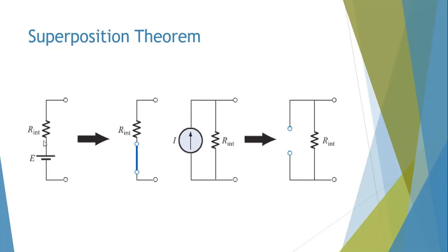So if you want to remove a voltage source, you short circuit it. Now the drop is 0. It's not contributing anything in the circuit. If you had to remove a current source in a circuit, it means you want to make the current flowing in this part of the circuit 0. You're going to open circuit it, because current cannot flow now. So just bear that in mind. If you want to write it down, I'll give you a few seconds. If you want, you can draw that.